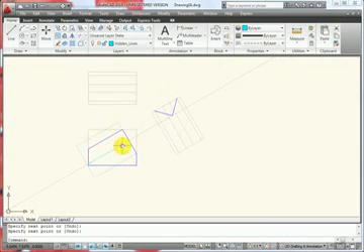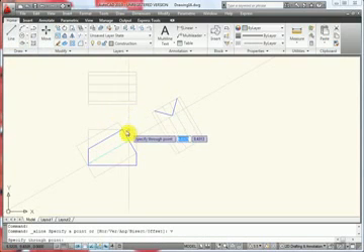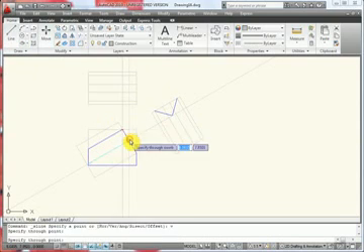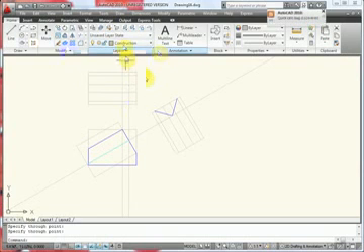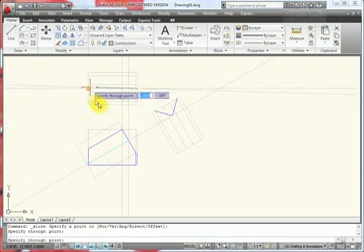The next thing I want to do is make some construction lines based off this point and this point. So I'm going to switch back to my construction layer and open up the construction tool. I want to make vertical lines, so I'm going to put a V and space bar. I'm going to choose this point and this point. Now I'm going to start filling in some geometry up here with the object layer. However, I want to make one more construction line that is through the center of this. Notice I just snap with the triangular, which is the midpoint of this line, which would be the center.